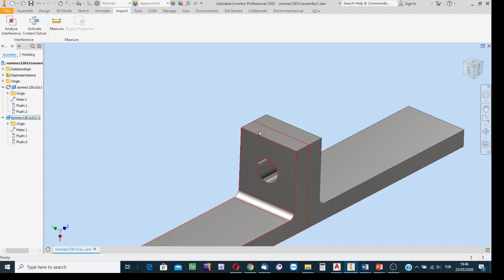Okay, thickness of the part, this and the other, 8 millimeters, 8 plus 8, 16 millimeters. We need to consider the thickness of the nut because through the hole of the nut the stem is to extend. It is 10, almost 10. 16 plus 10, 26. Okay.